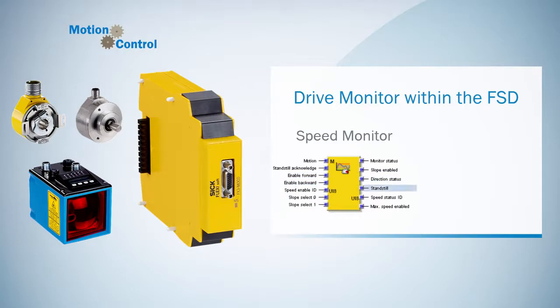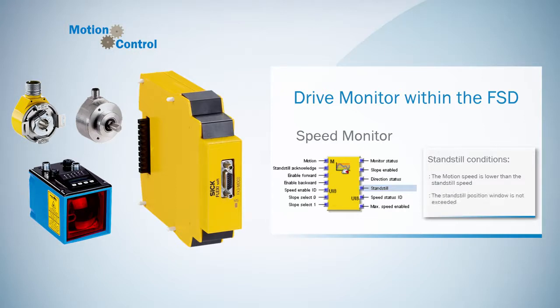The output standstill indicates if a standstill is reached. In this context, it goes high if the standstill conditions are met. This happens if the motion speed is slower than the standstill speed for at least the duration of the standstill acceptance time, or the standstill position window is not exceeded.